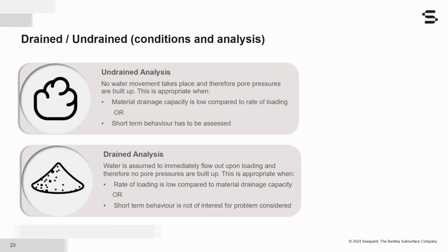So I've used a lot the terms drained and undrained, right? But what do those terms actually mean? Undrained means that no water flows, so the volume of voids in saturated soils remains unchanged, and the soil density also remains constant. Now, since water is essentially incompressible in comparison, of course, with the soil skeleton, any imposed loading is transferred directly to the pore water, and it is transferred as, of course, excess pore pressures. And the effective stress remains constant, while any attempt to impose volume change is resisted by the excess pore pressure changes.